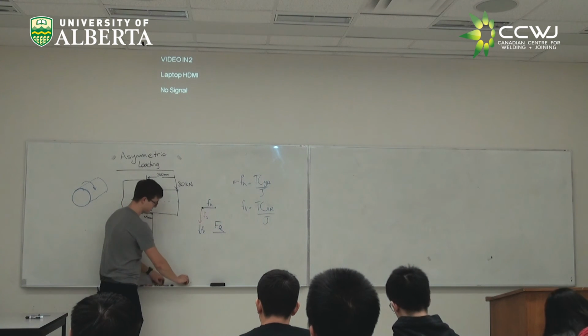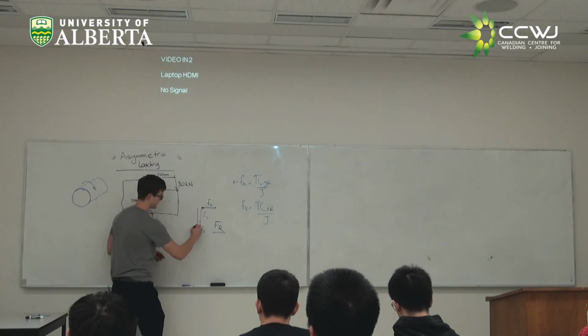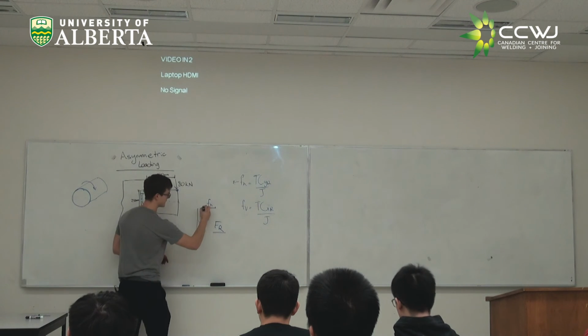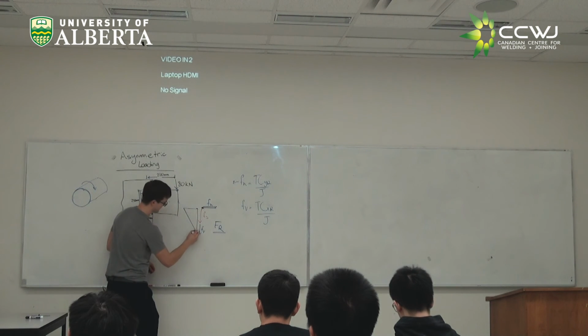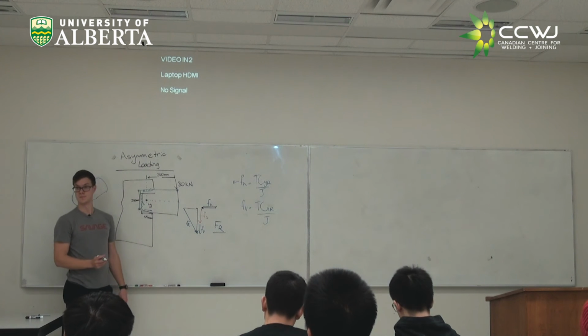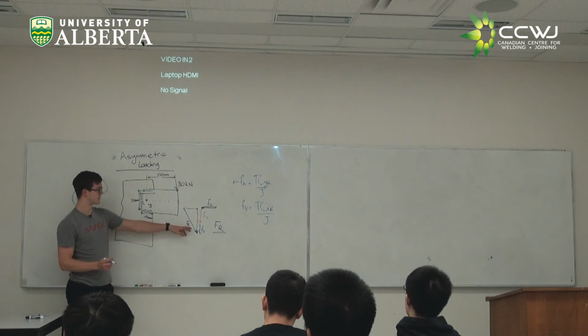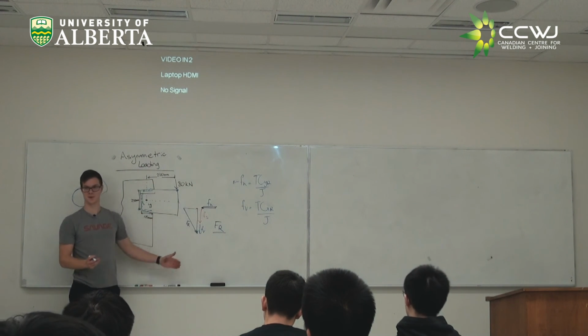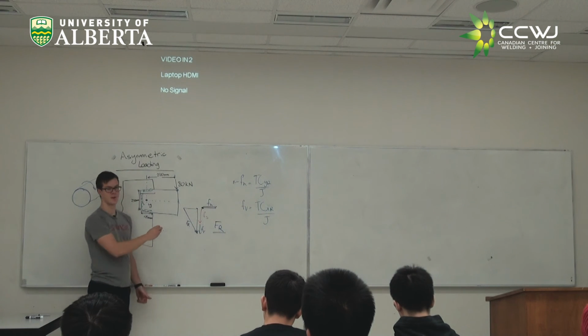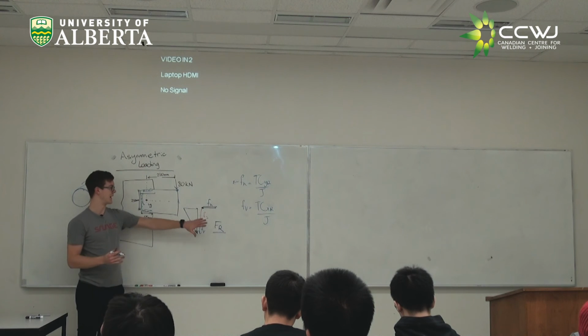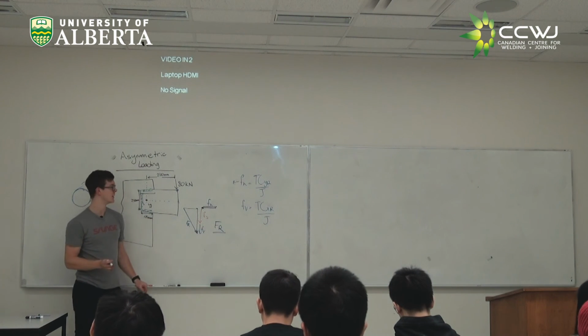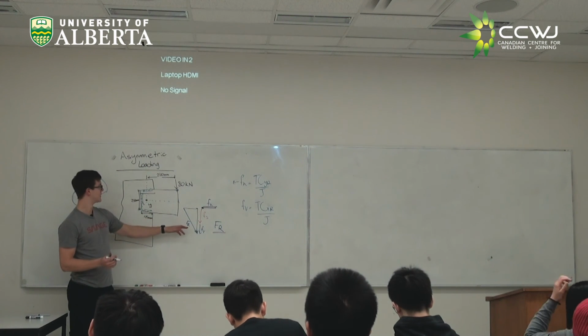And this FR is what happens if you take this load here as a force and this here as a force, and if you add them end to end, that's going to be your FR. So you're looking at, okay, this is horizontal, this is vertical. You end up with FR is the square root of the sum of the squares of those components, and that's your resultant force.